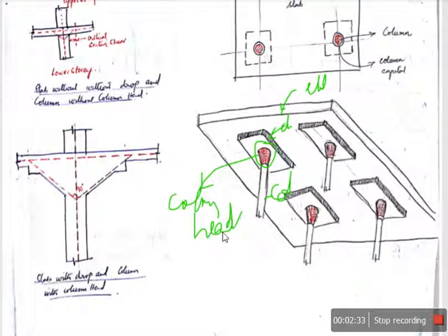So if the span is more, because the bending moments are more, you get huge dimensions of the beam itself, and the beam becomes a girder. For a girder, the main criterion is self weight. If the self weight increases, the weight of the entire structure increases, so you get larger column sizes, larger and deeper foundations, and all those sorts of things.